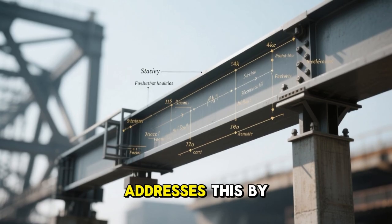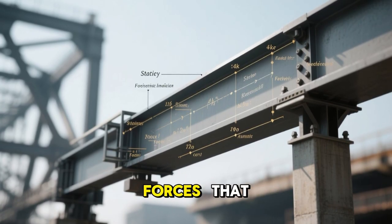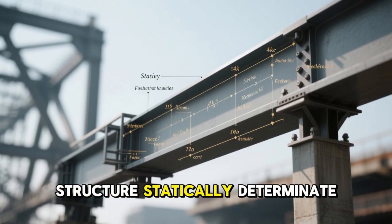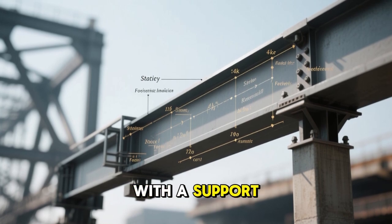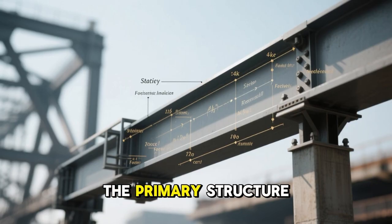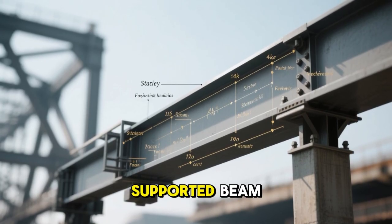The force method addresses this by identifying redundant forces, reactions or internal forces that, if removed, would make the structure statically determinate, for example, a fixed end beam with a support removed. Example: if a fixed end beam is the primary structure, removing one support creates a simply supported beam.